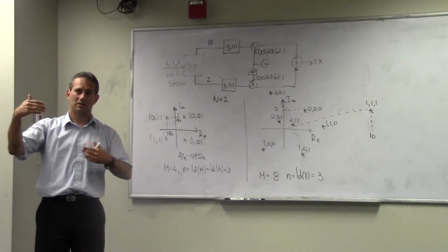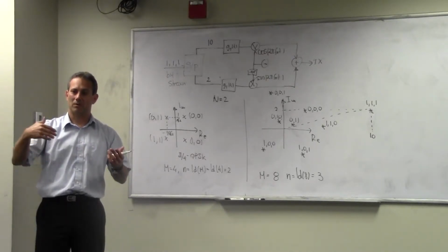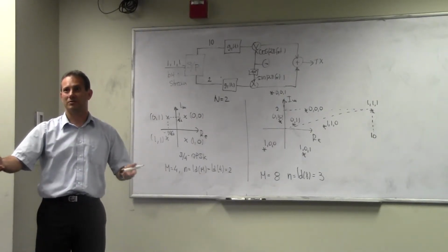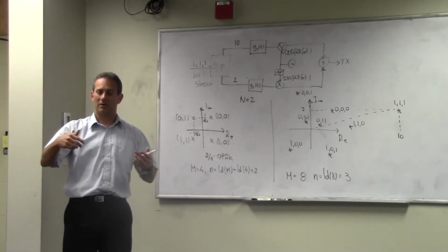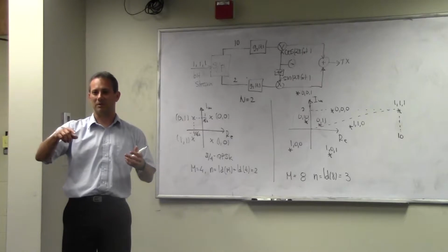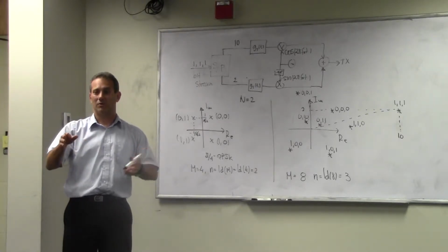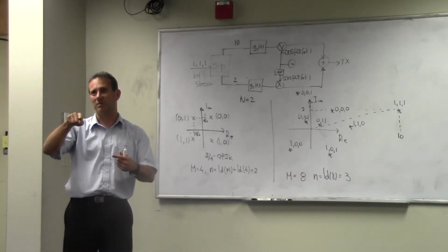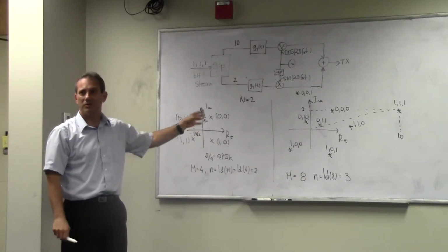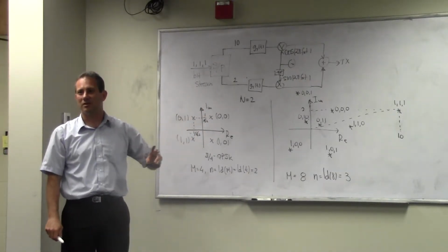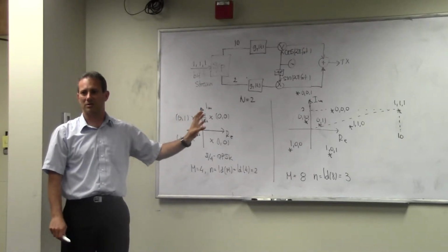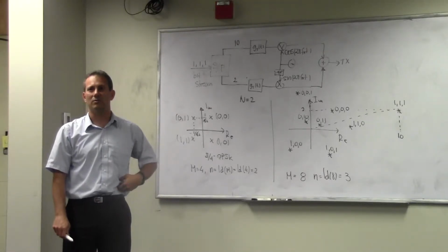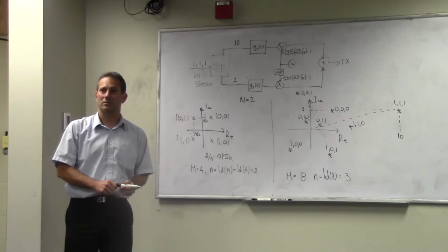For example, if you look at some other channels, like if you're working through optical channel, then you really just go ones and zeros, right? Light or no light. So there's no sine and cosine there. Or if you're like Dr. Murshid, he does something that's called spatial multiplexing. So over there's no sines and cosines. You're getting different dimensions by using different portions of the optical fiber. So that's why I'm kind of still dragging this psi 1 and psi 2 to handle the general case. But for most of the practical applications, at least in the current state of technology, we use sines and cosines. Just there's nothing better suited that we know of for analog waveforms.